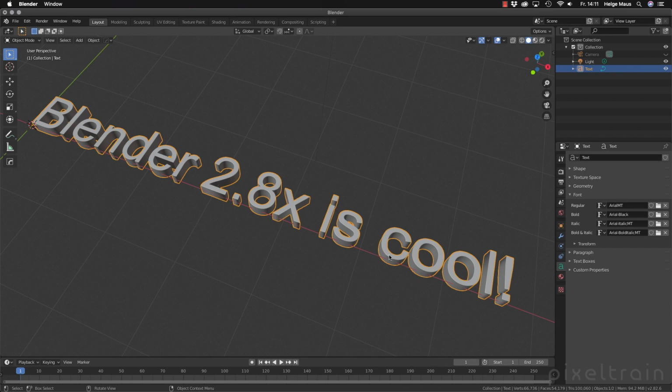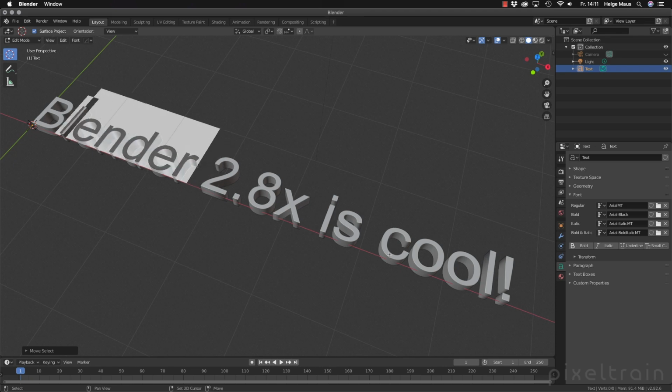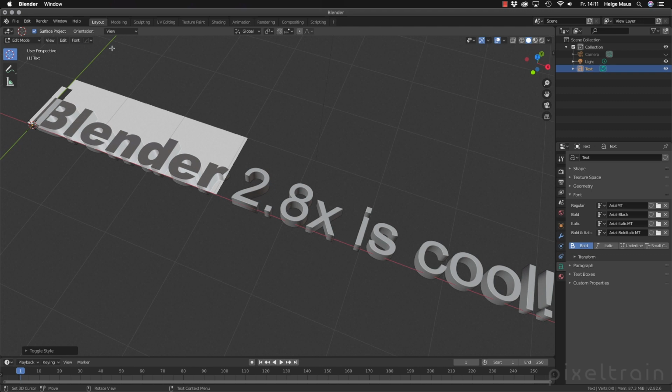For this, we go again into the edit mode. And if you now go over your text with your arrow keys or with special keyboard shortcuts, which you can read up in the help file of Blender, I can now select, for example, the word Blender here. And now I have a little font menu and keyboard shortcuts. Control B, for example, for bold, Control I, and so on. And now I can make this, for example, bold. And now we have a bold Blender here.